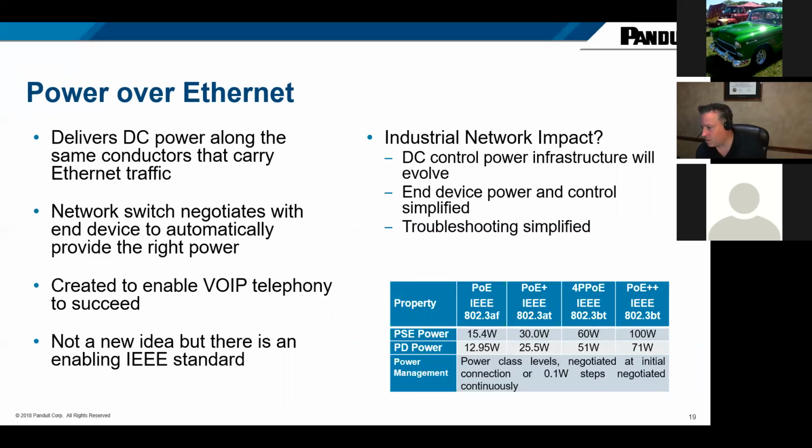If you look at the little table in the bottom right, PoE AF, 802.3af, the standard PoE, is 13 watts delivered to the end device. The top number is the injected power from the source, typically a switch that's enabled with PoE, and then the delivered power is the 13 watts there. So that's your standard PoE.